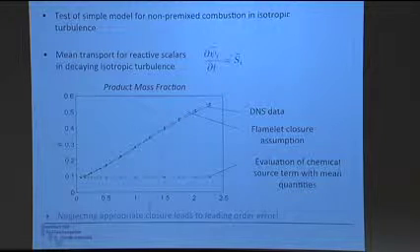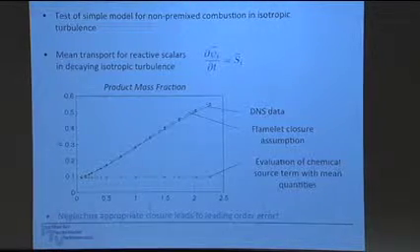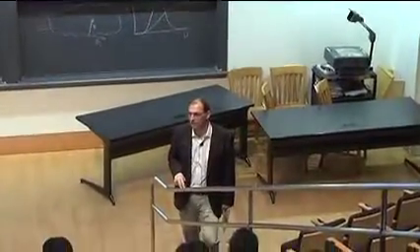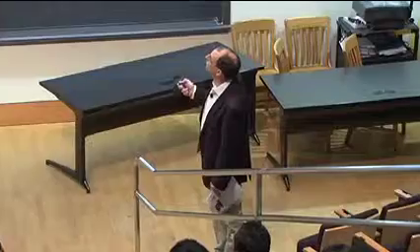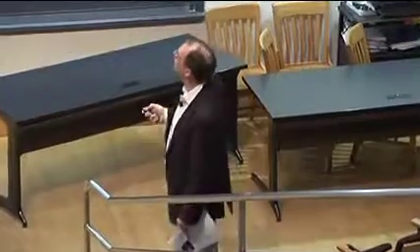And now, in most of the commercial codes you use, when you want to do a turbulent combustion problem, they tell you to just solve detailed chemistry, and they don't do any closure of the chemical source terms. They just evaluate the source terms with the mean that's computed from solving that equation. So just solving moment equations and closing this with a mean, that is wrong. That's all I want to say.